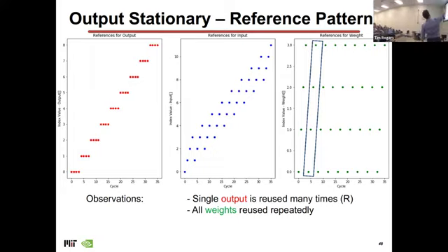I mean, in terms of sheer numbers, it's not necessarily better, right? Because there are 4 elements in both. So there's this repeating pattern where I go through 4 elements of the weights, and then I reuse those 4 elements. So in theory, the reuse distance is 4. The reuse distance is also 4 in the activations, but remember I had way more activations.